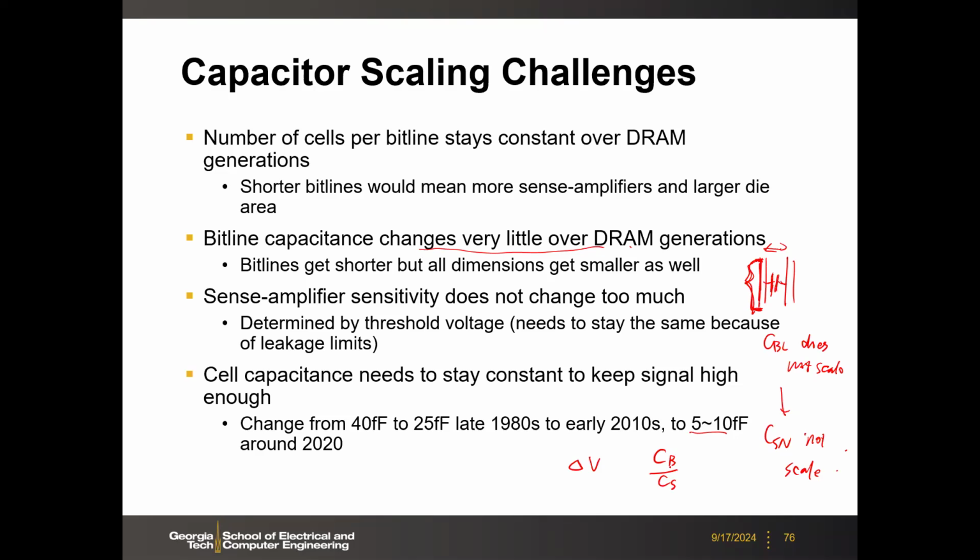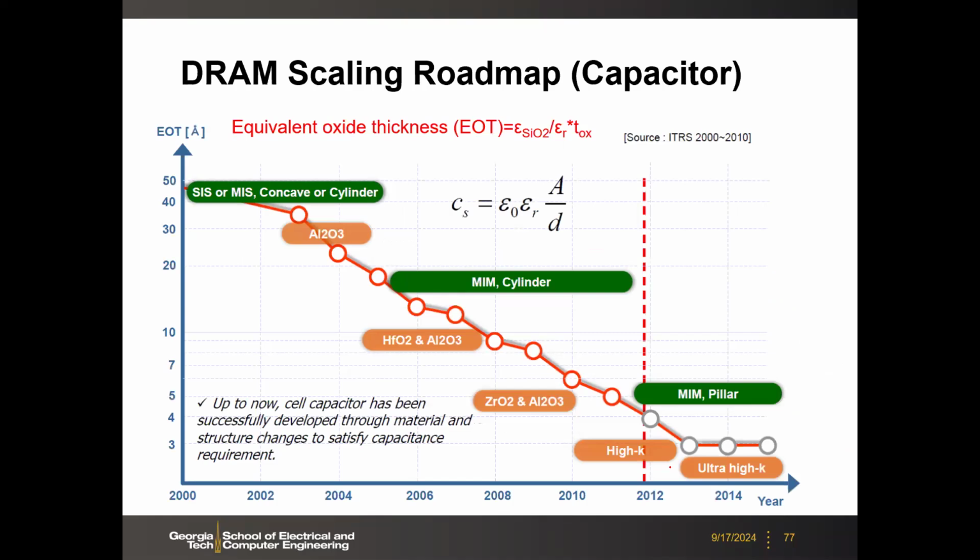As I said earlier, the DRAM subarray size is typically 512 to 1,000 along the bit line. On the word line side, you can have even more, but on the bit line side, typically 512 to 1,000. This is larger than SRAM, which is like 128, 256. In the CSN, mainly we are increasing the height. We are going to show in the next few slides how to maintain that.